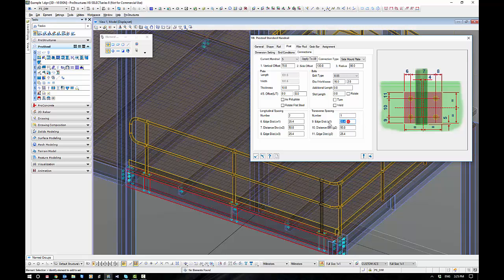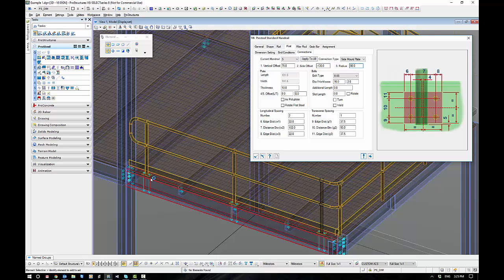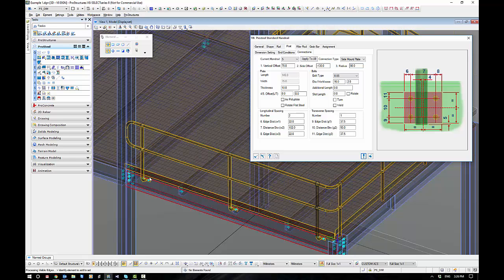Okay, so I'm just going to run through and make a couple of these settings. This transverse, I want that 70 mil, so 37.5 each way. I'm going to make that 50 mil centers, but only one bolt, so it's ignored. 102 centers the other way, giving me 146. Okay, so update that, and that should give us our side offsets. Just set in a negative value there. All of this is just trial and error too. Just pull up, go have a look, make sure you're happy with it.